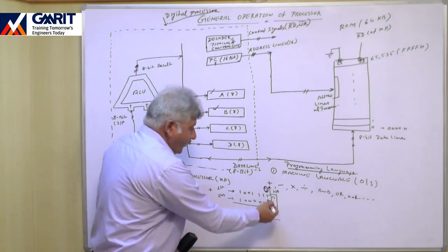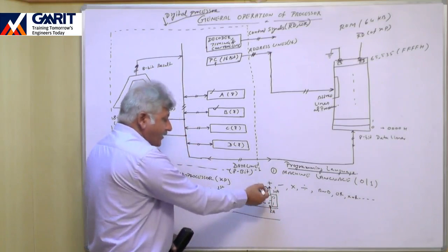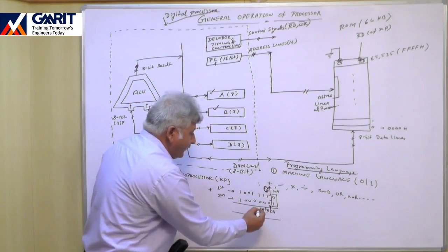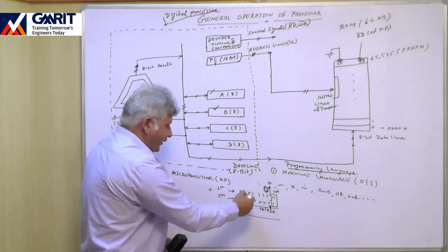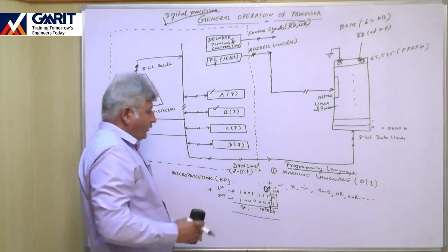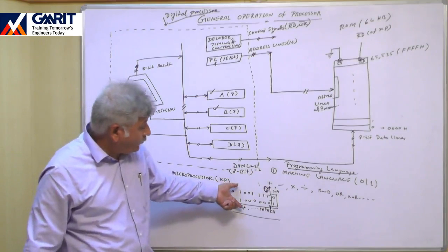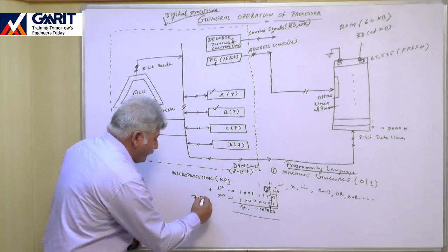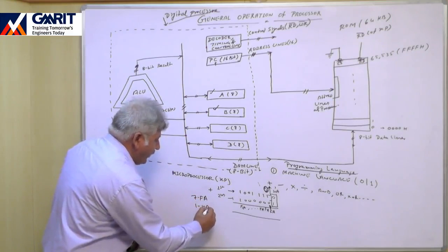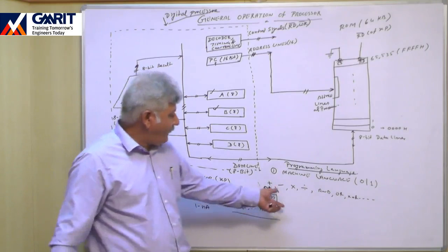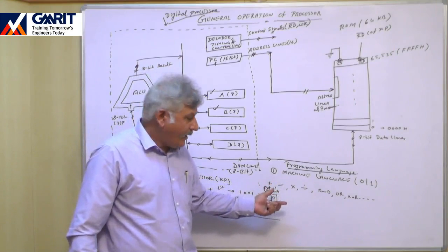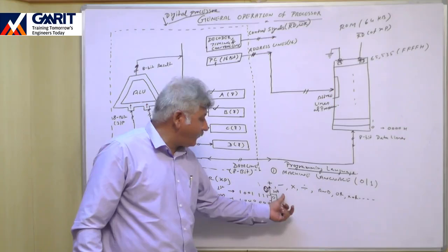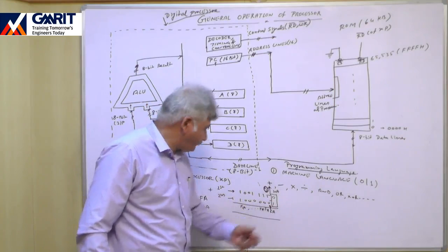Now in the same way, there may be a possibility when you are adding these two bits, one carry is generated. So here also you require one full adder, and here also, like this. At every addition point you require full adders. So when you want to perform addition over two 8-bit numbers, basically we require 7 full adders and 1 half adder. In place of the half adder, we can also use a full adder, and in that case we can keep the carry input of that full adder grounded, 0.